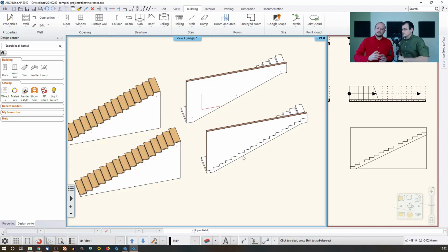One thing to highlight here is that the left-hand side, what you see, is automatically regenerated anytime you make changes. When the staircase changes inclination, for example, because the left-hand side is based on a rule setting, it automatically updates itself until the wall can reach the staircase. The right-hand side is a custom tailored drawing that you have created, so it won't automatically follow the changes when the staircase changes inclination, but you can update the profile by simply repeating this same step and then just join them together. That's right.